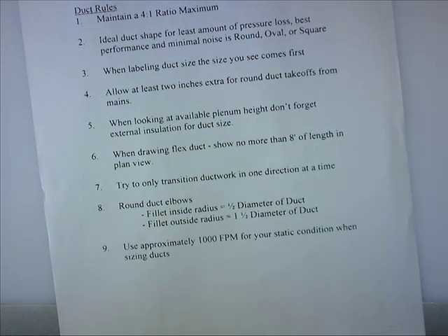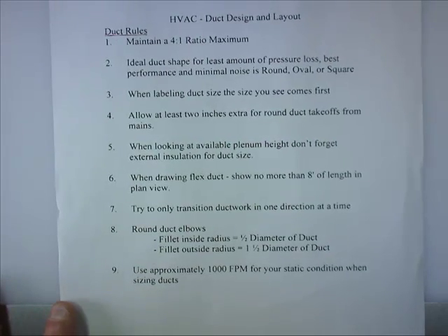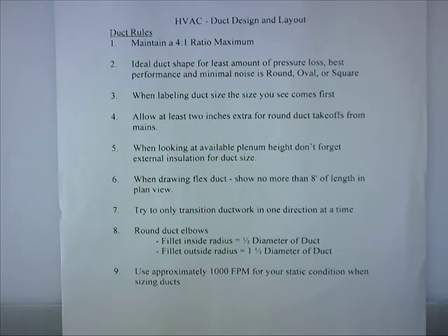There is one other thing that I didn't see on there that's probably on this one, but I'm going to, yeah, it is, number 5. So we'll worry about that whenever we get to it. The very first thing for duct rules, maintain a 4:1 ratio maximum.